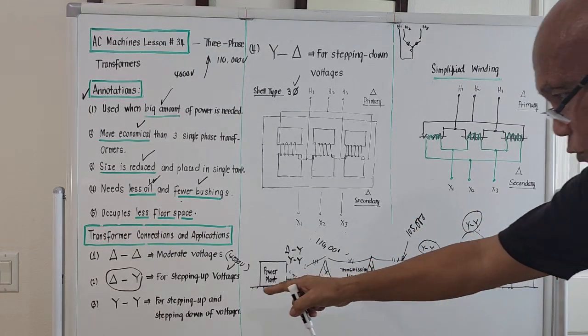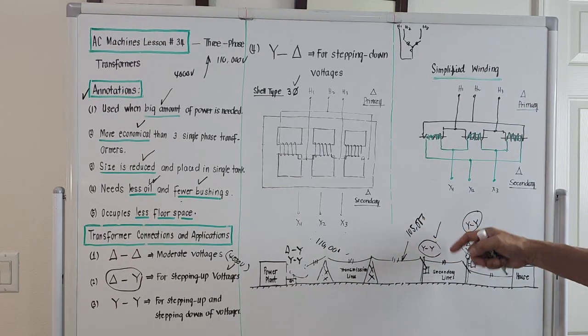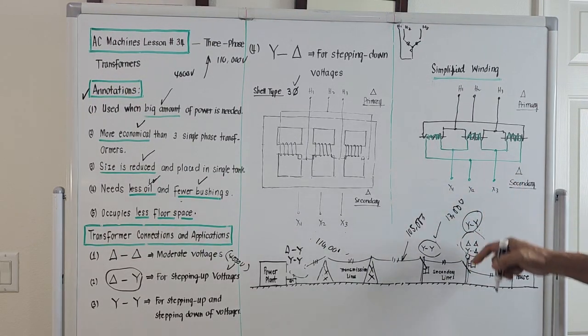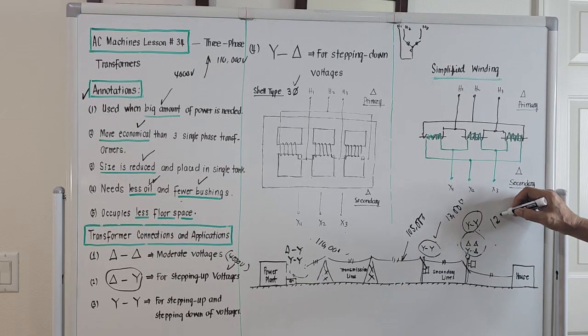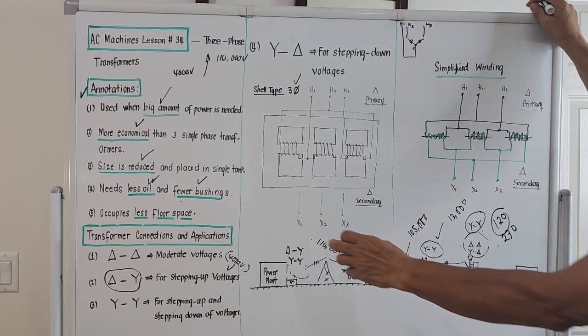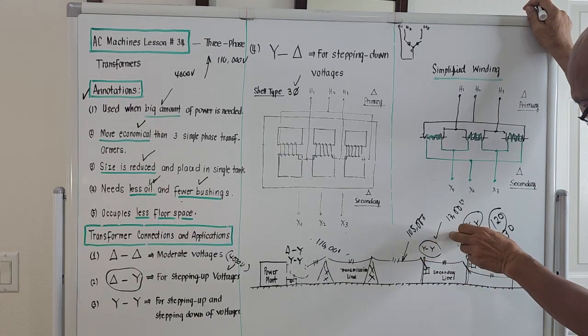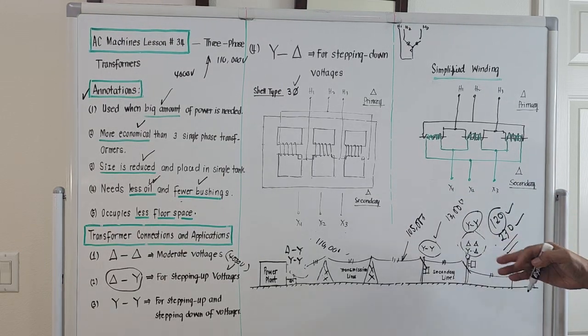So the other location of this YY will be maybe here to reduce this 105,000 to a certain voltage, maybe 13,000. And the input to the transformers over here will be 13,000, and since these transformers are stepped down, this 13,000 could be reduced to a voltage of already 120 or 230. So a big one, we step it down, again we step it down, and the output will become 120 or 230 to be safe for us to use.